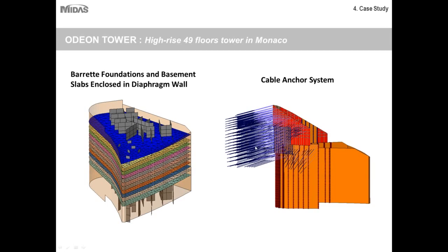I know that these three past projects are all higher end projects. They're large scale, so numerical modeling was necessary, or was the best solution. But just keep in mind that numerical modeling can also be used for smaller scale projects or conventional projects. As I said before, it's very useful to use numerical modeling programs to check the results of conventional methods or to account for other factors. And because of the quality of the numerical modeling programs that are out today, you can run numerical finite element analyses very quickly, much faster than you could in the past because of various features that have been developed with the programs themselves.